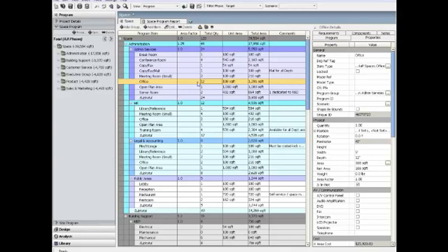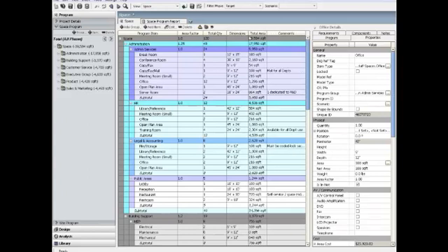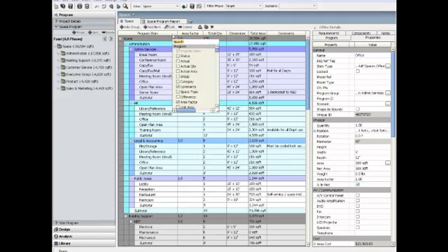In the Views pull-down, I can see a list of the custom views that are available. Affinity has several preset views that come out of the box and also allows you to create your own. When I open the view called Space, it will change the columns, in this case adding a column called Dimensions, which is appropriate since this view is focused on the properties and requirements for the individual spaces. To customize the views, I can right-click any of the column headings and select or deselect the properties or requirements that I want to show. Here I can select the unit area and target.